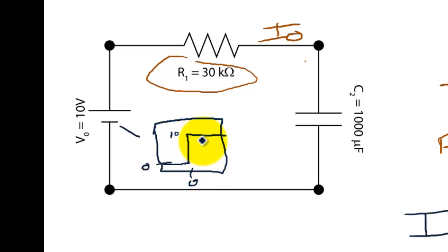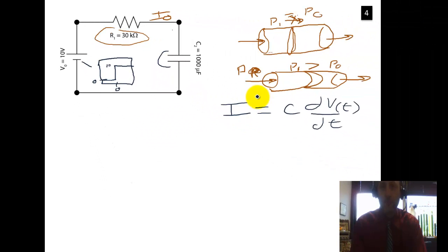So that's what we call a step change. So suddenly, there's a voltage difference across here. And if we have a step where we go from 0 to 10 in 0 seconds, basically, so this is all idealized, this is infinite, right? So in that instance, this capacitor acts as though it's not even there.